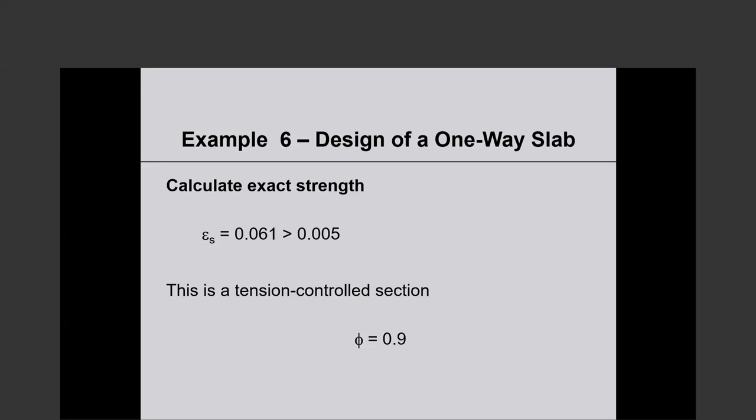So I am kind of surprised. So you designed an under reinforced beam, so it must have been kind of borderline. So let us say you targeted concrete strength of 4,000 psi and it didn't come up to 4,000 psi.